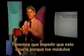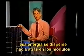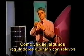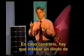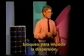We want to be able to prevent this from occurring because we've made precious energy from our modules. We don't want to have some of it leaking backwards into the modules and just radiating away at night. Like I said, some regulators may have relays or switches that open at night and prevent that leakage. If we don't have that situation, then you actually have to install a blocking diode to prevent this leakage.